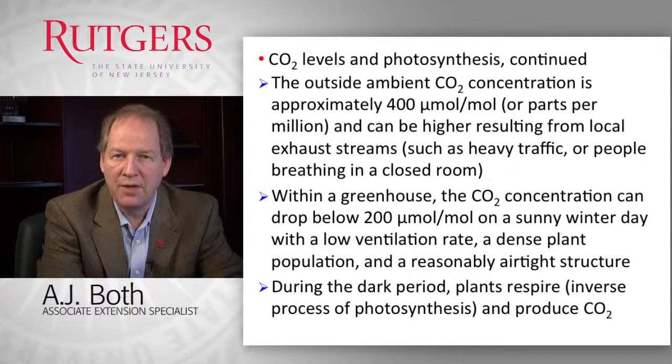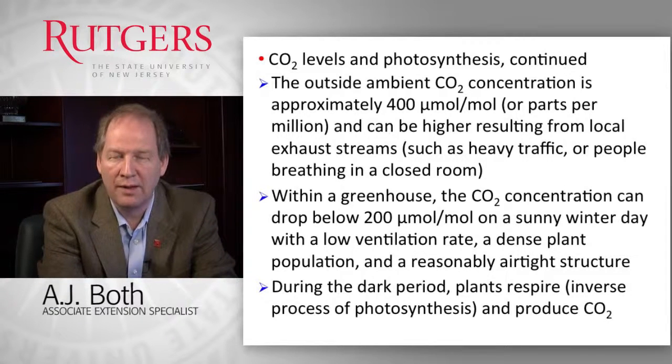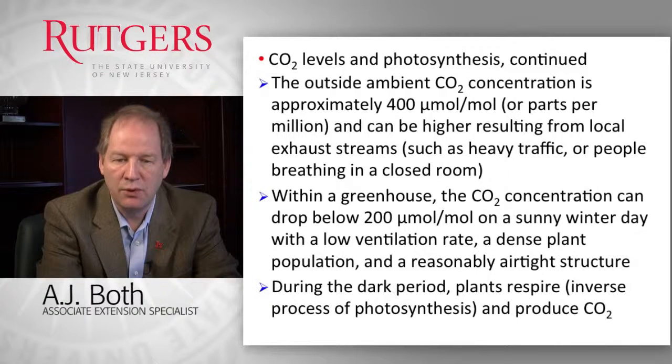As I mentioned, the outside CO2 concentration is about 400 parts per million or micromoles per mole, and can be higher in locations where there's a lot of traffic, car traffic or people traffic. In a confined area where a lot of people congregate, we can measure much higher CO2 concentrations than in well-ventilated areas, because obviously we expel CO2 as we breathe. We take in oxygen and we expel CO2.